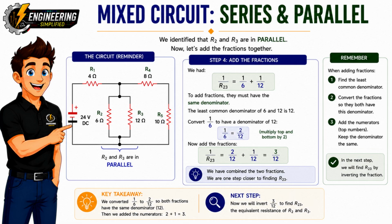Now both fractions have the same denominator, so our equation becomes 1 over R23 equals 2 over 12 plus 1 over 12. Adding the numerators gives 1 over R23 equals 3 over 12. We've now combined the two parallel resistor fractions into a single fraction. We're almost finished. In the next step, we'll invert this fraction to calculate the equivalent resistance of R2 and R3, replacing the two parallel resistors with one equivalent resistor.